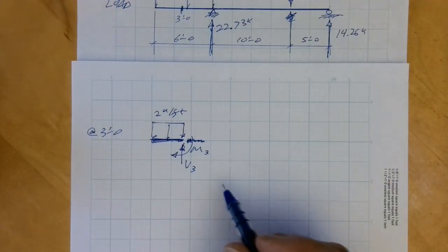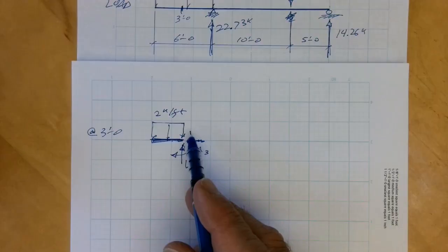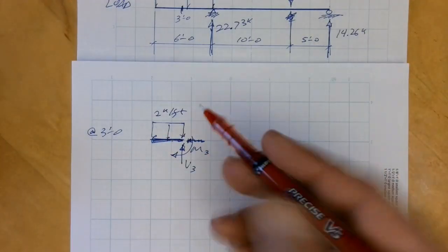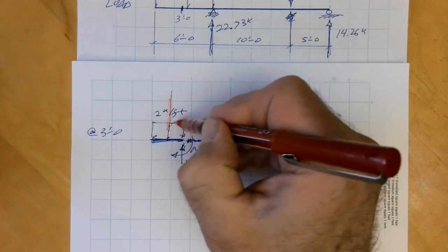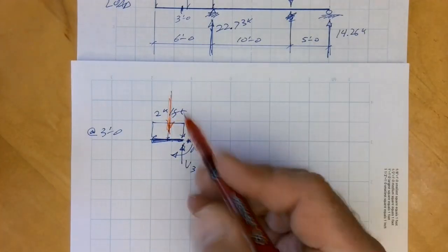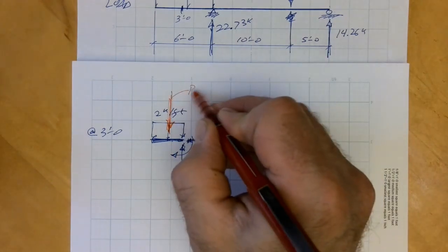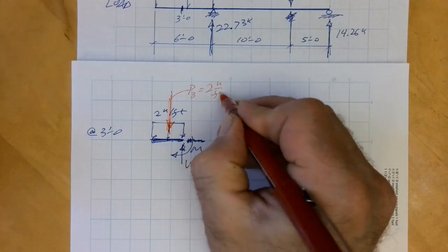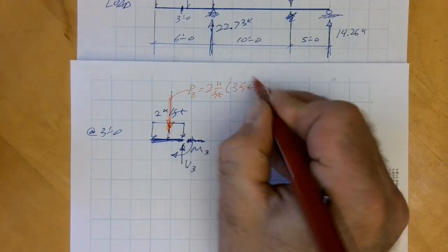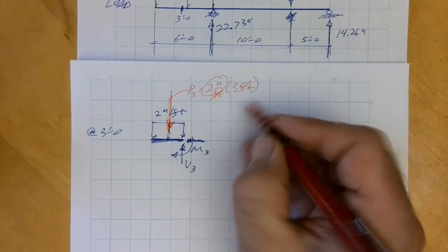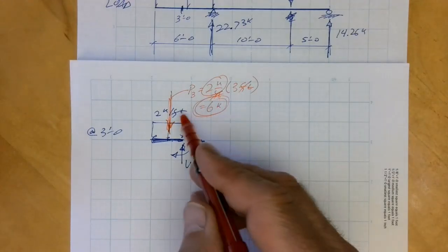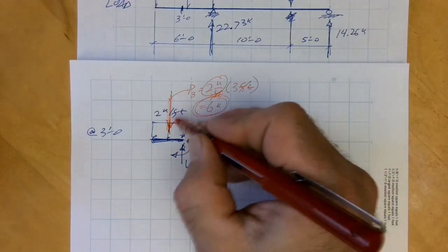The subscript we'll say relates to the length from the left end. Alright, well this is going to be a little hard to solve with a distributed load, so let's make this a point load, and this thing P3 is going to equal 2 kips per foot times 3 feet. Those go away, I'm left with kips, and it's equal to 6 kips. That's my downward force.